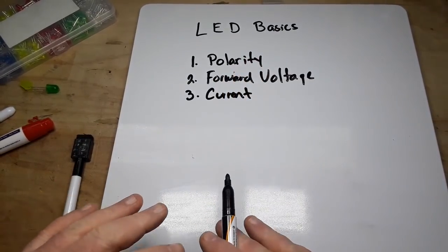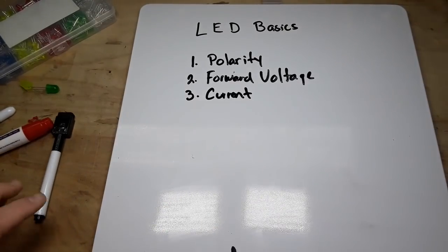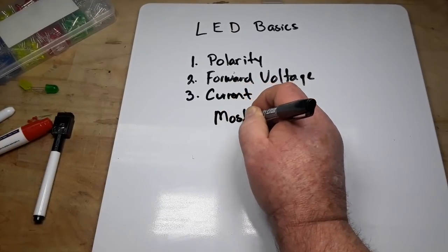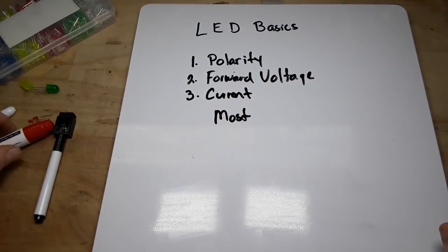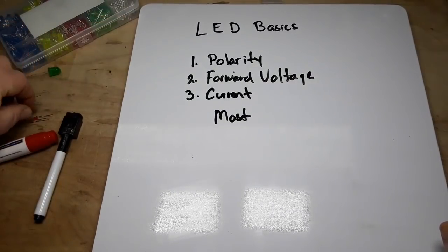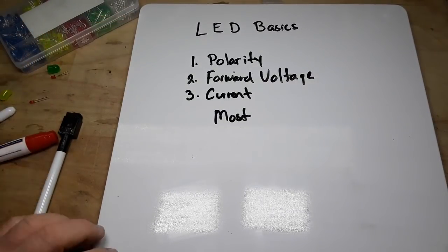The current is the electrical push. Diodes by themselves, whether they're signal diodes, power diodes, or light emitting diodes, do not limit current. They will take all the current you can give them, and when you exceed their breaking point, they will simply burn up.